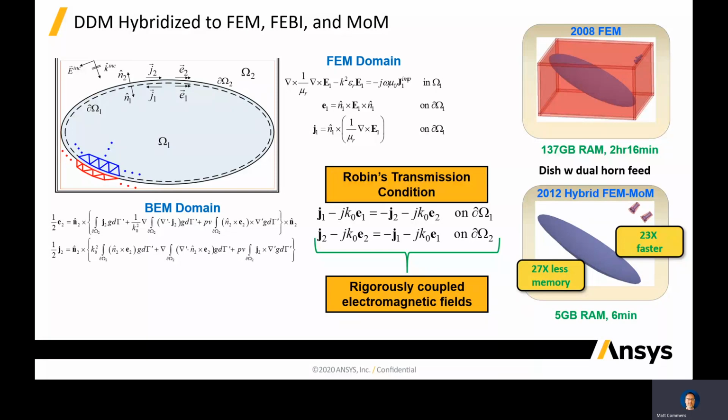FEM, when you have very fine geometric detail, dielectric, and method of moments when you have large conducting structures. We can combine them together in one system matrix and deliver an accurate solution. Again, fully coupled accurate solution.